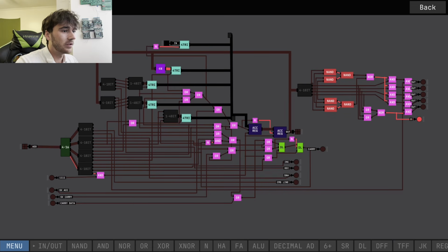This is the accumulator group. So if this is on and this receives a signal, then we operate it towards what we want to do. And that is, we can clear the accumulator, of course. We can increment it by 1. We can decrease it. We can shift it, which took an incredible amount of time right here because it shifts with the carry, which is such a minor detail, but it makes all the difference in the actual calculation. And then, of course, we have our 0 flag, so we can know if the accumulator is 0, and if not, we can shift it through. But yeah, that is how it works.